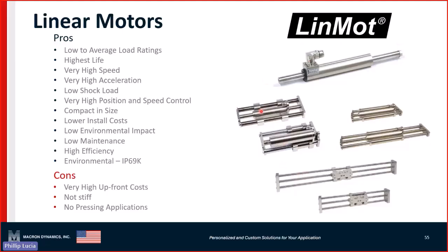You can get these where they have the bearing structures in place, without the bearing structures in place, but these things can literally run billions of cycles. Since it's basically a shaft, there's no gearing, there's no belts, there's no gearbox, so there's nothing to maintain in these, and they literally are just running on bushings and without any metal to metal contact that has to be maintained. So the pros are they do have average load ratings, up to 200 or 300 or 400 pounds.